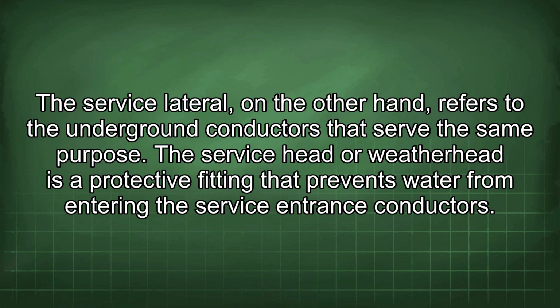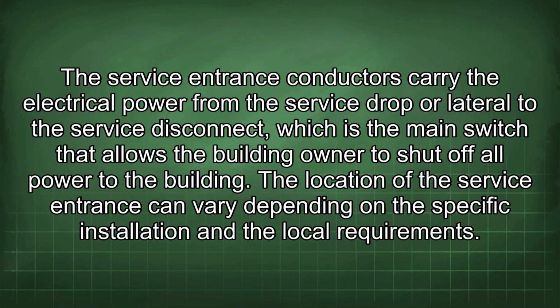The service head or weatherhead is a protective fitting that prevents water from entering the service entrance conductors. The service entrance conductors carry the electrical power from the service drop or lateral to the service disconnect, which is the main switch that allows the building owner to shut off all power to the building.